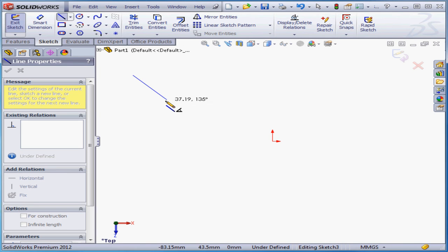Let's left-click to place the first point of the line. You can release the mouse button. Notice this rubber band effect. Next to the cursor is a feedback number, and what this does is give us an approximate length of the line in your current units of measurement, in my case, millimeters. A left click now would give me a 24 millimeter line. Let's move a little bit more. A second left click places the second point of our line.